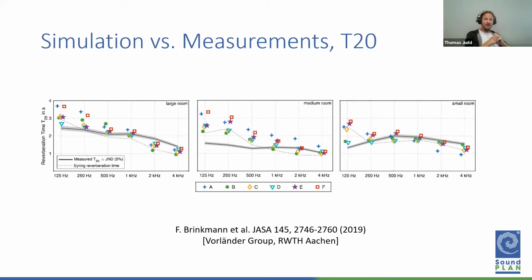They've got some serious experience under their belts, and this is just a little round robin of various room acoustic softwares compared with some measurements they did, and you will see that the discrepancies can very well be on the order of tens of percent. Sometimes you do a little better, especially at the higher frequencies, you can see, but you're very often outside the just noticeable difference.